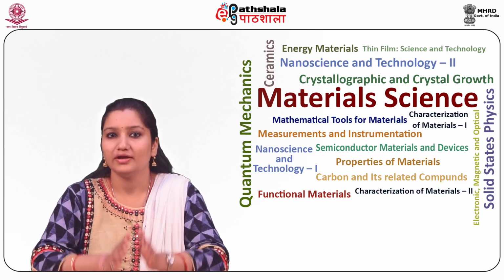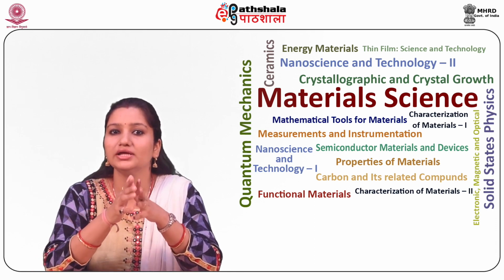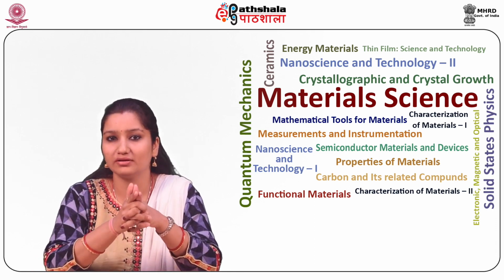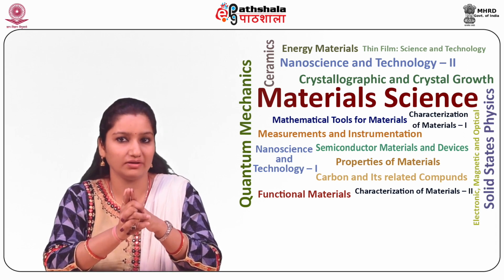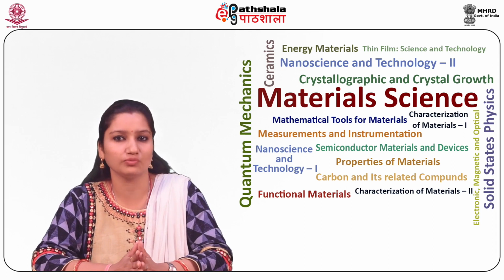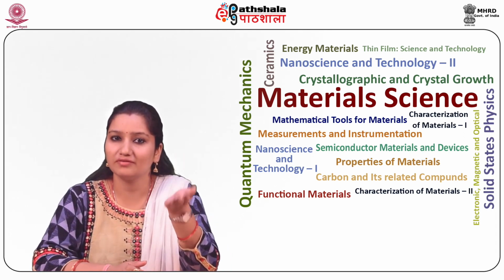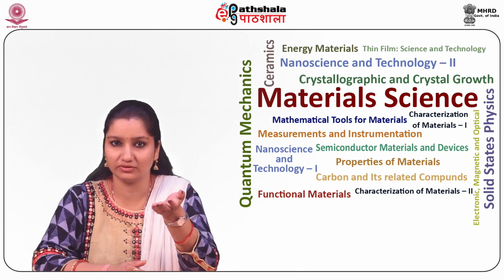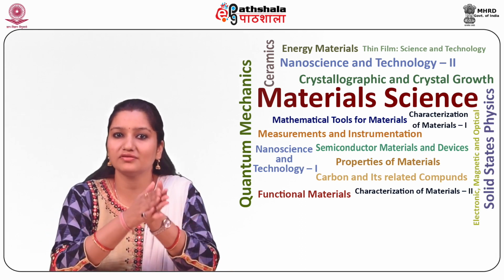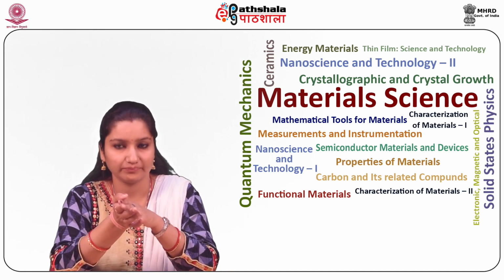The substrate is placed at the grounded electrode and is generally heated to 250 degrees Celsius to 350 degrees Celsius, depending on the film that needs to be deposited. In comparison, CVD, or chemical vapor deposition, requires 600 degrees Celsius to 800 degrees Celsius.